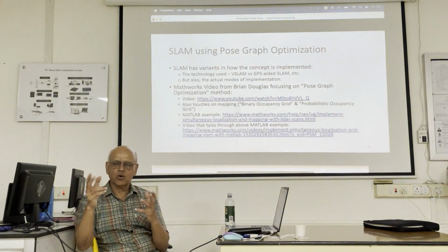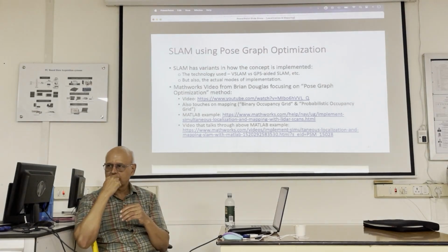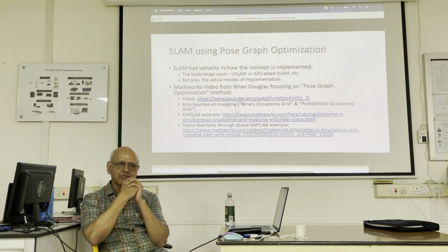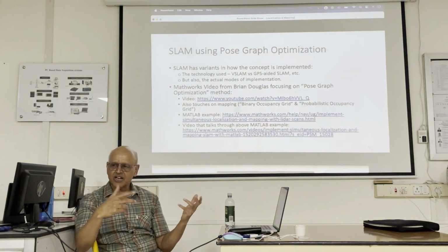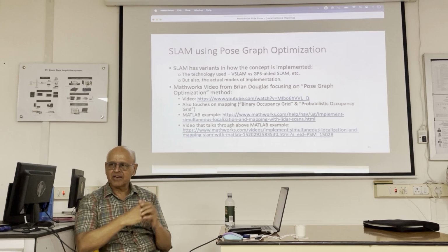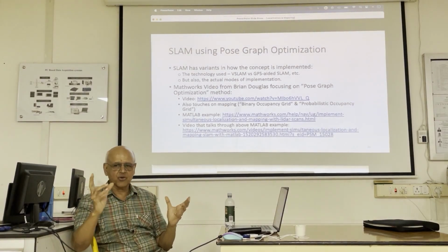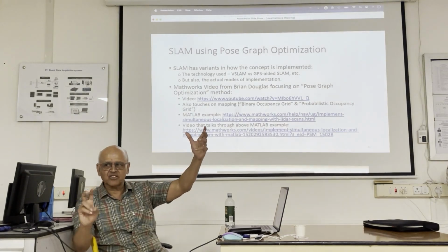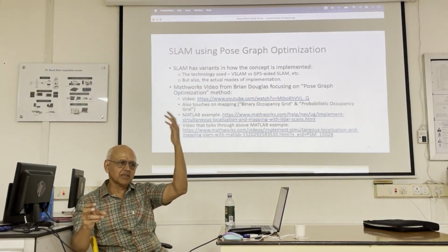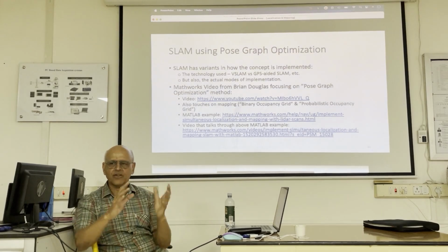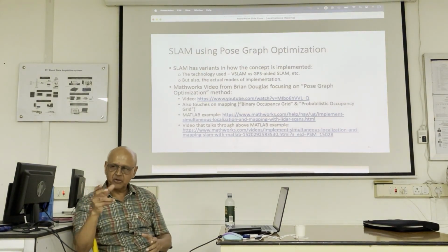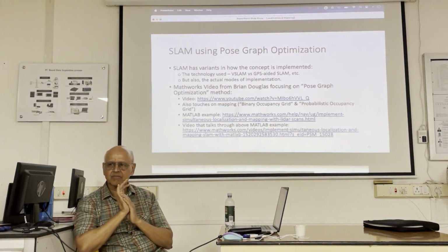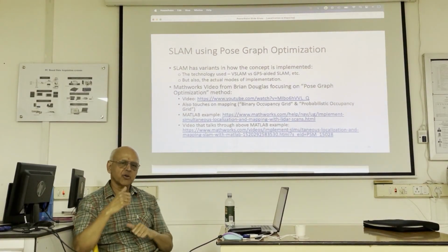And then you asked for the approximate value of KP. I said it's 0.01 or something in that neighborhood. Because if you put 1, the robot goes like this. And then you start questioning your whole algorithm. But if you've fixed the other algorithm, then you know it's got to be this, and you just change it. If you have mistakes elsewhere, this is not going to do anything, right? So it could be some other mistake, but typically, if you fixed everything else, you dial down the KP value, and you'll find it works perfectly. So if you can't get it, I'll show you my program next week.